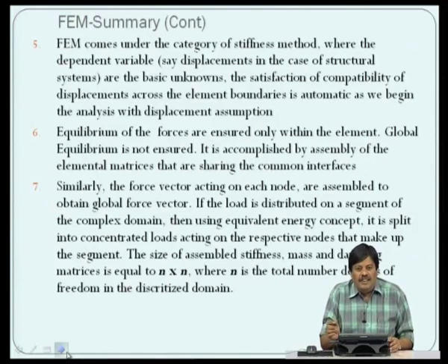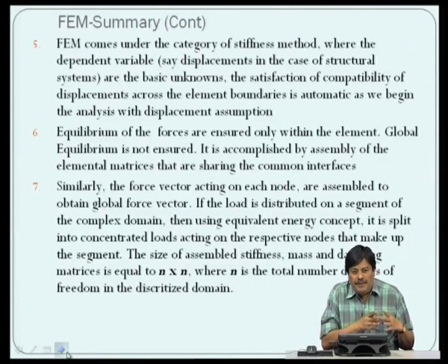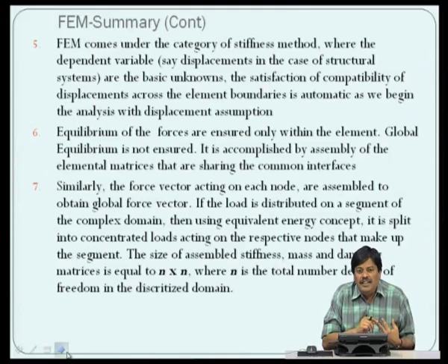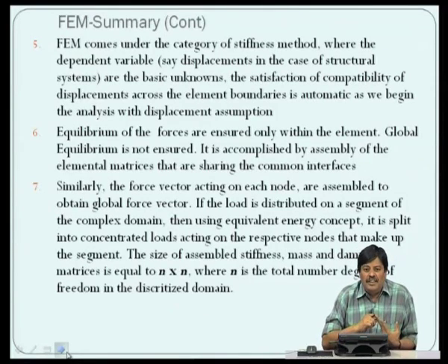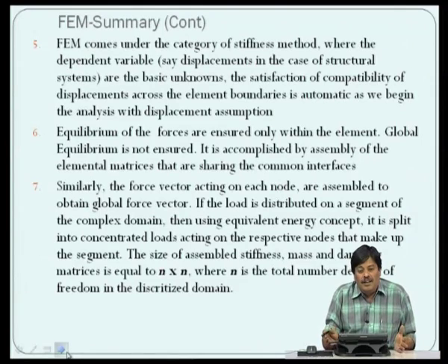So, basically there are two aspects which we said in the elasticity. One is the compatibility and the other is the equilibrium. Here the compatibility is ensured, whereas the equilibrium has to be enforced. The assembly of matrices will basically ensure that the equilibrium is satisfied.